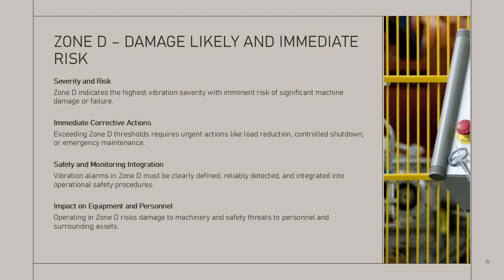Engineers must ensure that Zone D alarms are clearly defined, reliably detected, and integrated into operational procedures. While standards provide guideline values, real-world application requires careful consideration of machine design, failure modes, and consequences. Zone D emphasizes the role of vibration monitoring as a protective measure that supports safe and reliable plant operation.